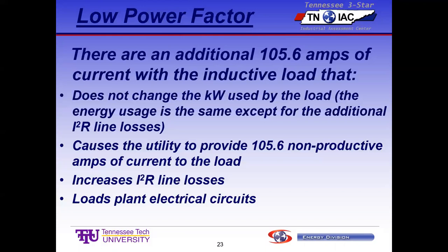Okay, so you've got this MCC, and right outside the door, they want to add another electrical component, another motor, another gizmo, another fan, whatever it is. But that MCC is full. It's pulling its rated power, or there's not enough extra capacity in that panel to provide power to that motor. So if they're going to put that there, they have to expand the MCC. Well, that's an extremely expensive project. You have to redo the electrical service to that portion of the plant.